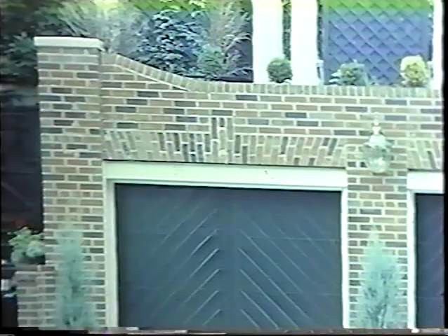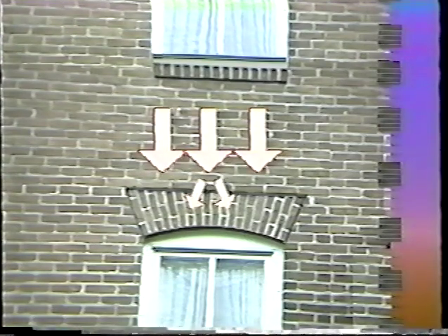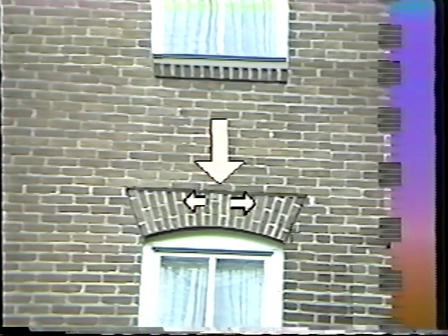The structural design of an arch is a complicated procedure. The arch should be designed by a structural engineer only. An arch works to resist vertical loads by transferring the vertical load and developing horizontal forces or thrusts. The vertical load and the thrust to be resisted depend on the arch span, the arch rise, and the magnitude of the vertical loads applied.